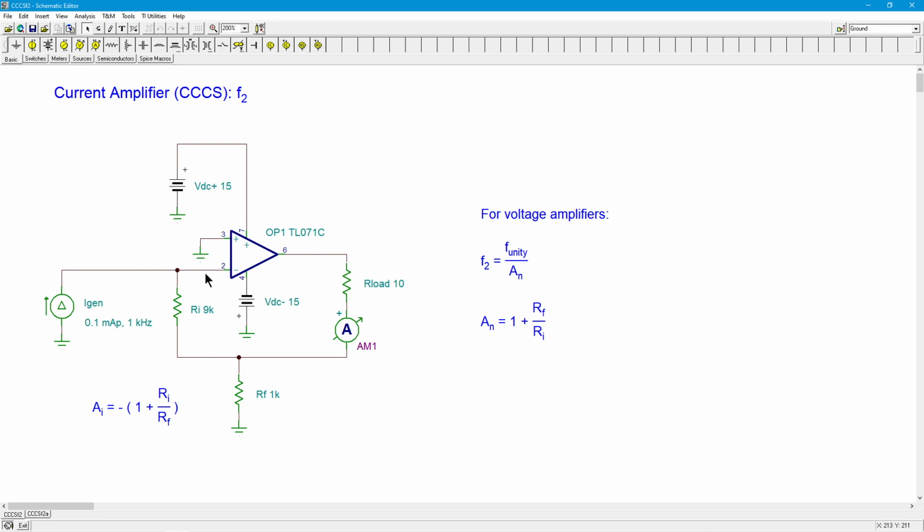And the Ri, if you think of a non-inverting voltage amplifier, goes from that same point, the inverting input, down to ground. Okay, I've got a resistor on the inverting input, but it's not going to ground. I don't have a single resistor going from here to here. How does this match up? Well, it doesn't. So how do I find a noise gain?